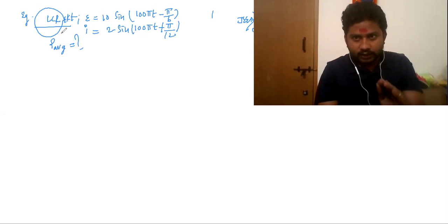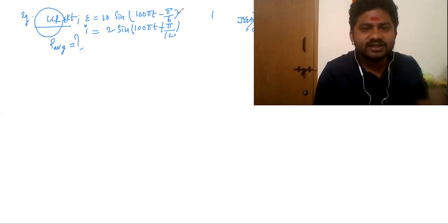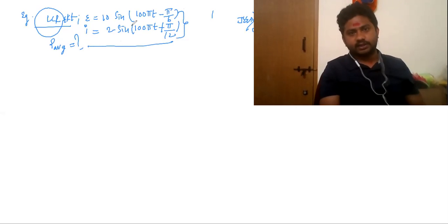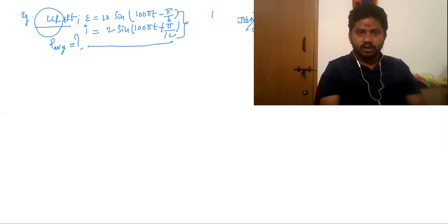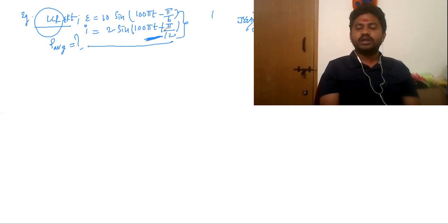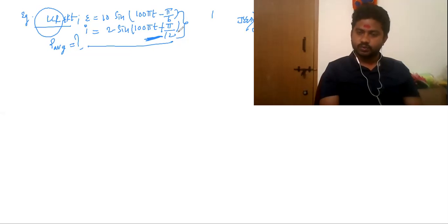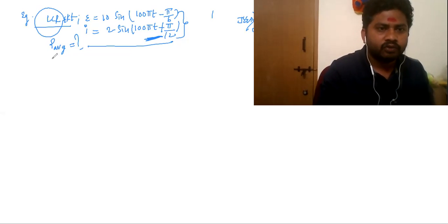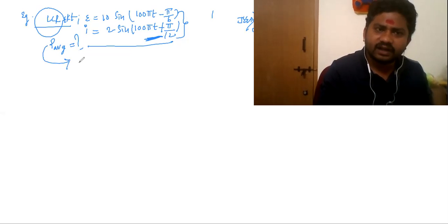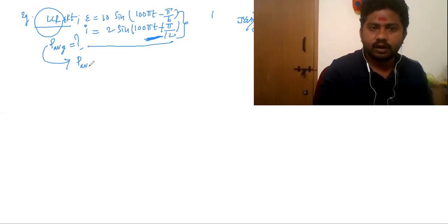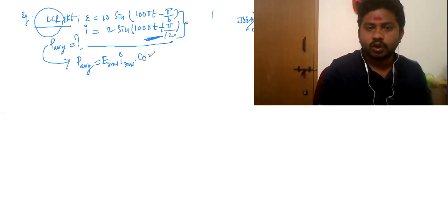And see, they have not asked, but I am asking you: what is the element dominating in the circuit? See here, current is leading. Current leading is possible in a capacitive dominated circuit. Yes or no? Yes, right? So now, whatever it may be in an LCR circuit, I have clearly given you the average power consumed here is ERMS into IRMS into cos phi.